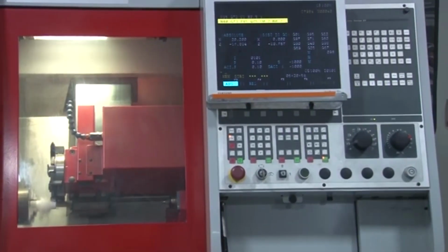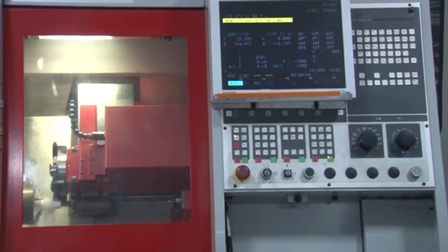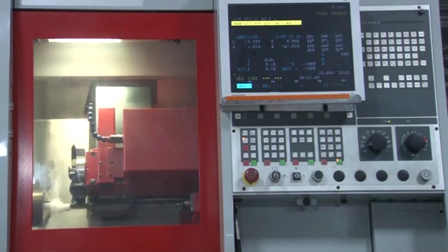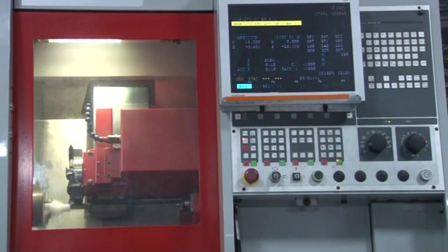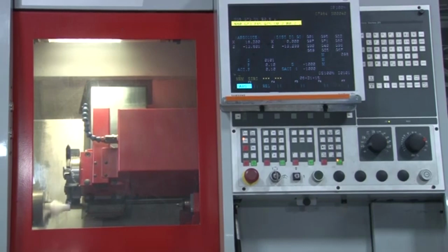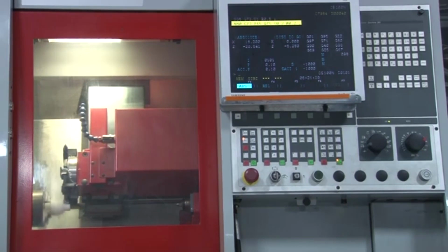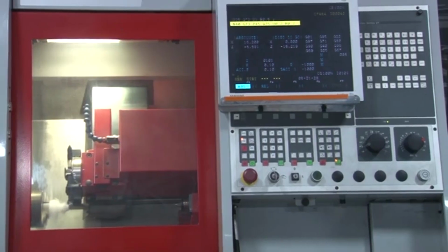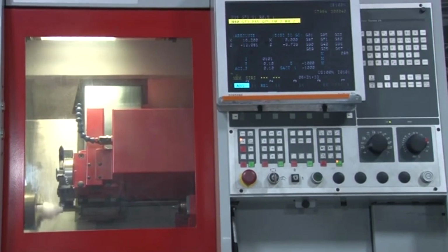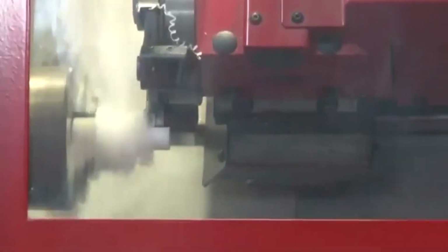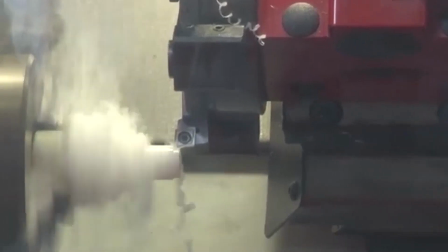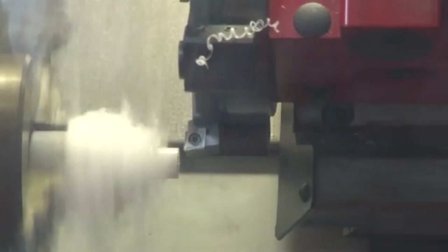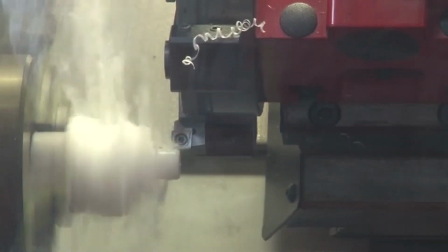We have given a particular coordinate for x and z, it will move up to that, and that is why there will be no clash between the tool and the 3-jaw chuck, because according to the program it will be moving. It will go up to that point as per the program, and then it will come back. So, there is roughing in the beginning, rough operation, then there is the final finish operation. This is how the final diameter has to be achieved. Okay. And it has been done in different passes.